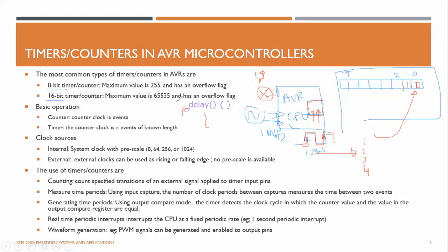In your program, when it meets a delay function, it will rotate in here, like a small while loop, right? So if it is a 1 second delay, it will not do any other work. Like there are some other codes in the bottom. It won't go there. It will stay here without doing anything, right? But sometimes we don't want the CPU to just be busy here.